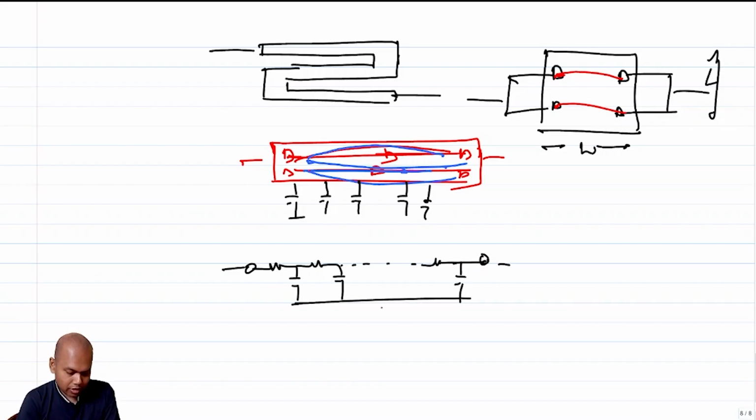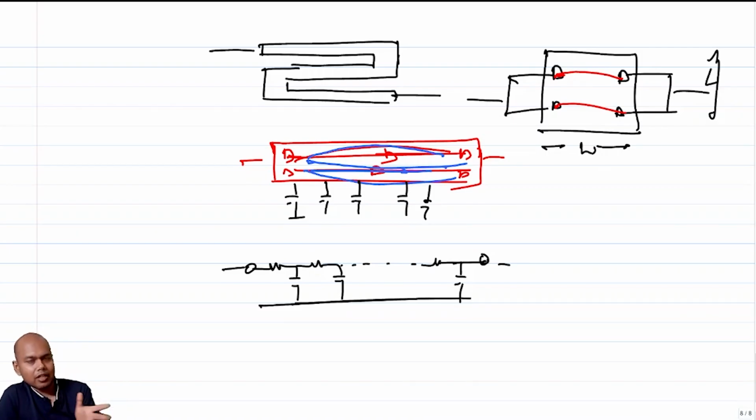So when you are simulating or when you are taking up any PDK, if your resistance values are of importance, ensure that you simulate it once and see that it has frequency characteristics modeled, right? If it's just a resistor which is as good as an ideal resistor, that probably will not be able to capture many of the frequency effects that you might want it to capture, right?